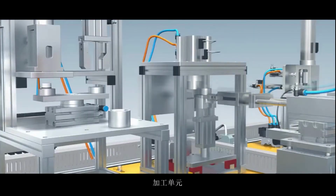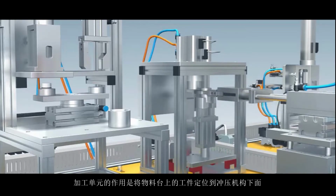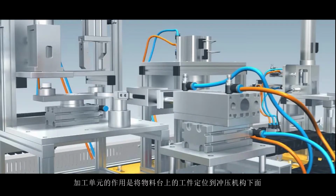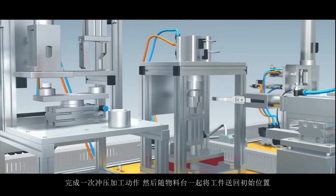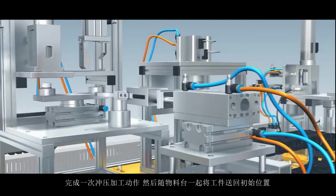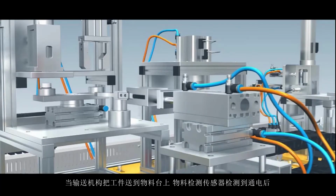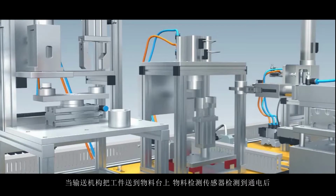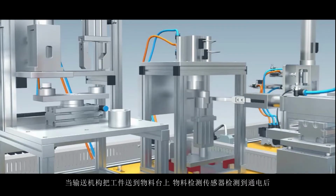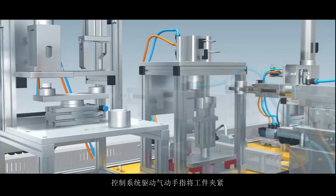Processing unit. The function of the processing unit is to locate the workpiece of the material table to the stamping mechanism, complete a stamping action, and then send the workpiece back to the initial position with the material table. The grasping manipulator device of the transport unit is removed. When the conveying mechanism takes the workpiece to the material platform, the material detection sensor detects it. The control system drives the pneumatic finger to clamp the workpiece.